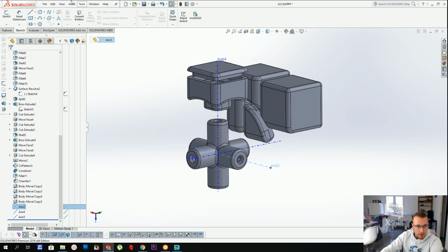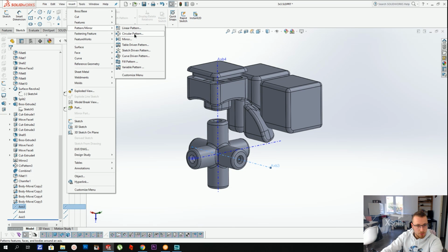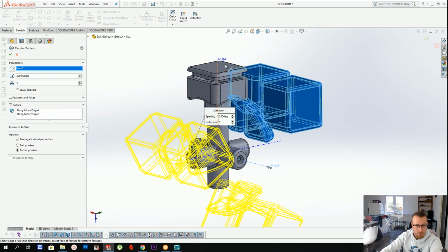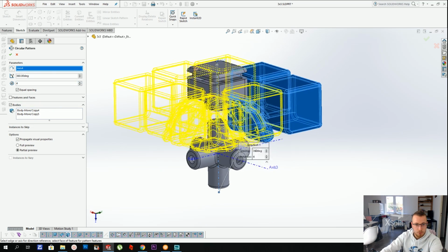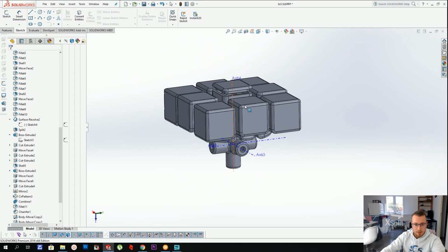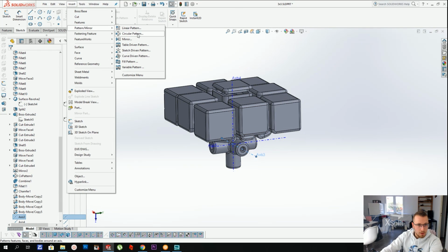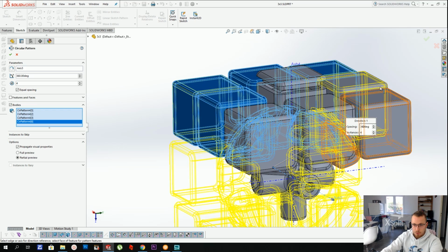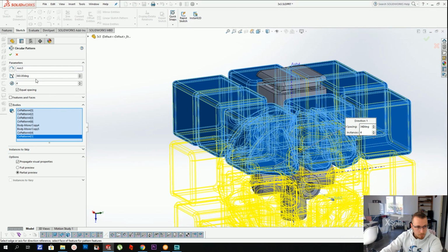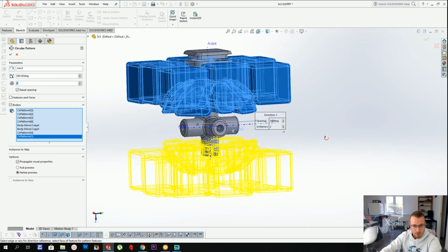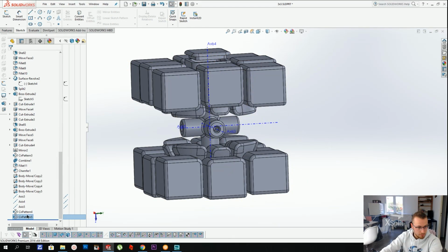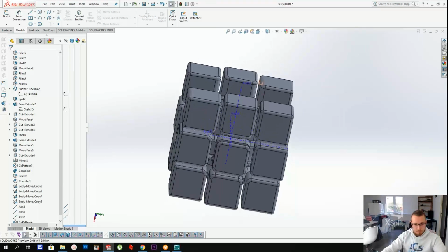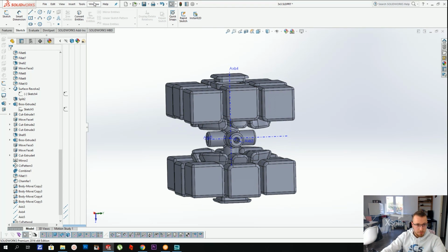And let's just do a circular pattern where I'm going to repeat this edge and that corner around this axis and make 4 copies like that. And then I'm going to use axis 3, make another circular pattern where I'm going to select all those edges and corners that I've just created, repeat them twice around 360 degrees. So you've got, oh, I forgot the center. I need that center too. Okay. And now I just need to finish it off.